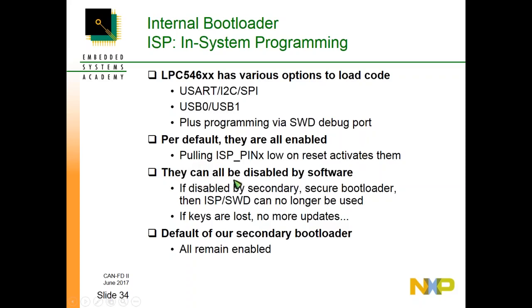Now think about that for a minute. No, I won't give you a minute. If everything is disabled, then you are closing down this backdoor completely and entirely relying on whatever software you have installed in the device. So if you use our secondary secure bootloader and switch everything off, yes, it works fine as long as you have the keys. If you lose the keys, sorry, no more updates.